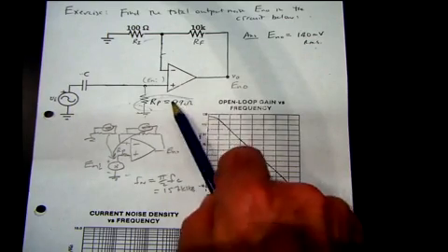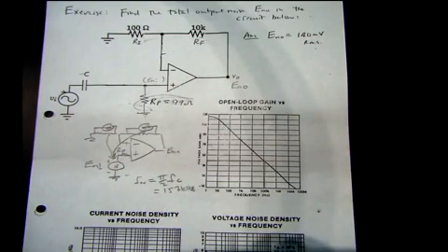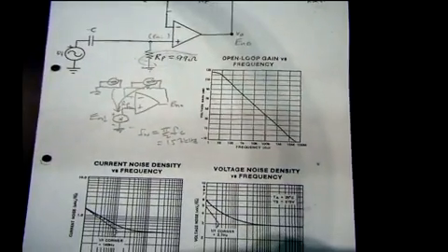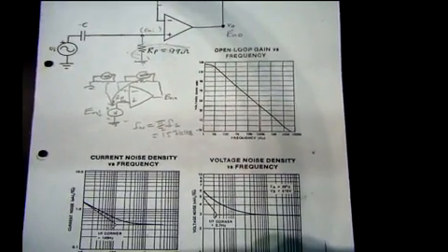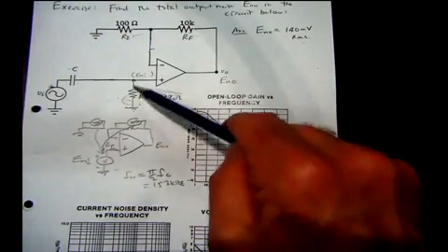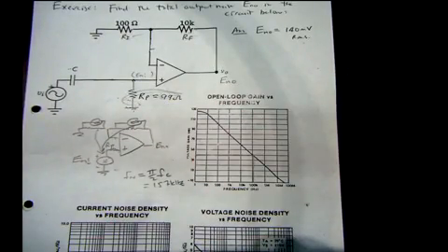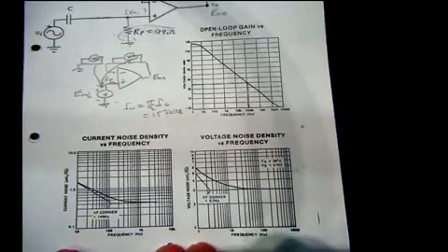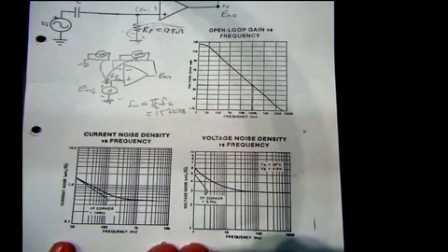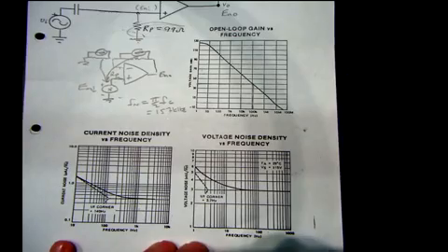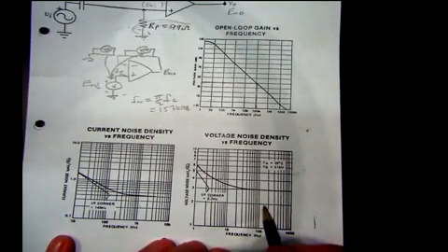That's why this one's 99 to match those other two. So that'll be relatively small. We also need the thermal noise of those resistors, which is likely to be also relatively small. So let's just have a look at the voltage noise and see if we can make some sense of it.